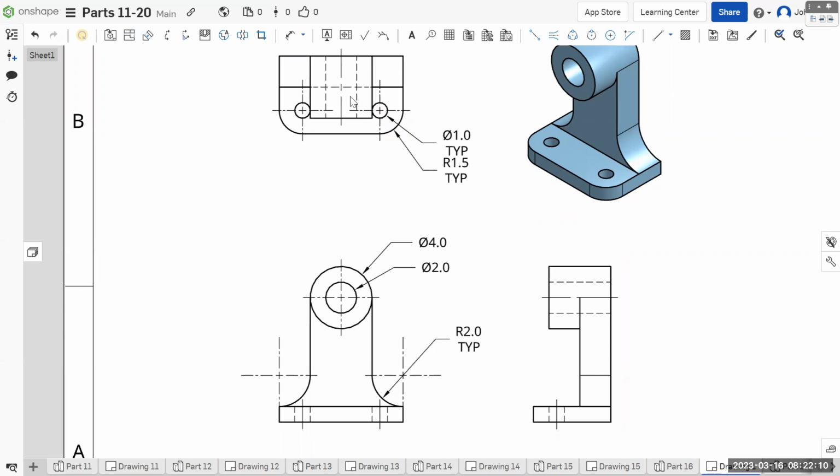Now we just need location of all the round surfaces and then double check for linear dimensions. So on the front view, let's count this as our anchor point because, just like before, we'd count everything from the left. Distance from here to this center mark gives us that.